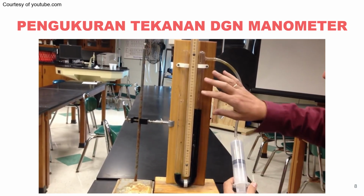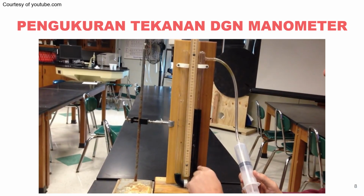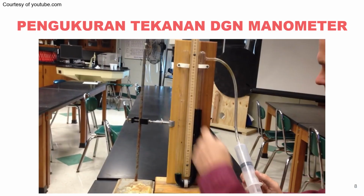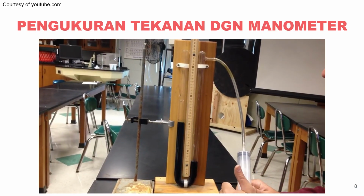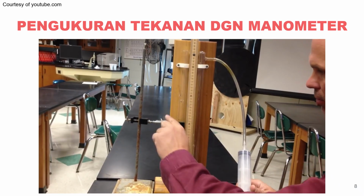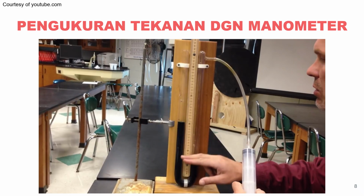So this pressure here is lower. Clearly you can see the atmospheric pressure is winning by 190 millimeters of mercury. Okay, and again, the pressure in here is 760 minus. When we did the other side, we did what? We increased the pressure. We said, well, this is pushing back on the atmosphere, plus it's supporting the column. So this is equal to the pressure outside, but you have to add 190 to it in this case if we're going to use that.